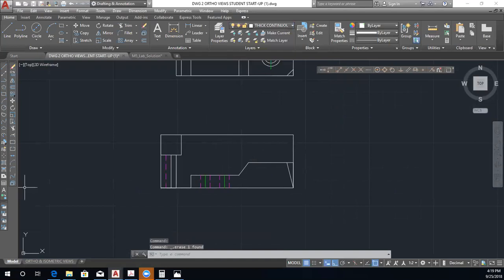All right, and then we can go through and then draw the called holes over here. So we know that those holes are located to the right by 0.8750. So 0.8750, and then we can just draw a big center line up to the top, just for our reference. Okay, so we'll do a center line. Awesome.